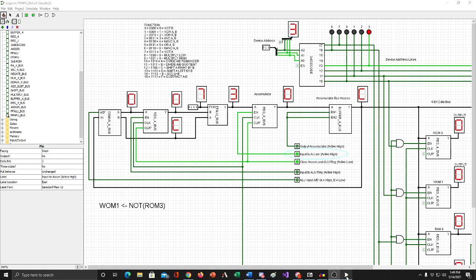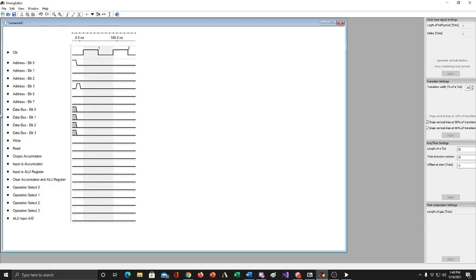Of course in your case, you've got to decide what was on that read-only memory. In my case, that means at the moment, the data bus contains the number 3, which is a 1, 1, 0, 0 in the least to most significant. Okay, so we've got that accurate.